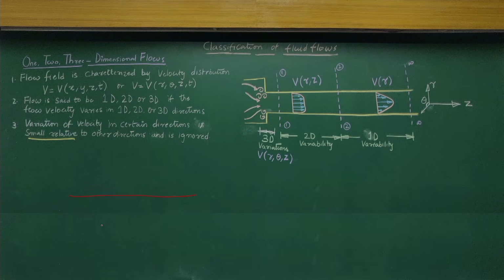Let's say I have a straight pipe flow. I can consider the flow going through it as more or less 1-dimensional. But if I turn the same pipe like this, then definitely I cannot say that the velocity distribution at this point has only one component; it will have 2 components, one in this direction, another in this direction. So there are multiple velocity components in the pipe flow, but the dominant velocity will be much larger compared to the other velocity components.